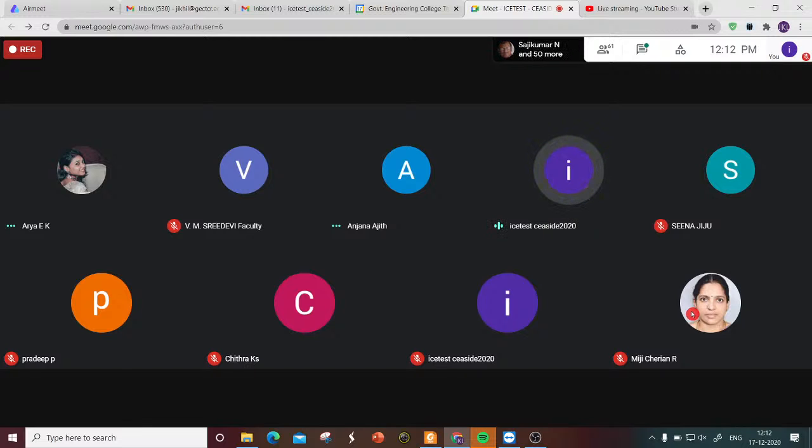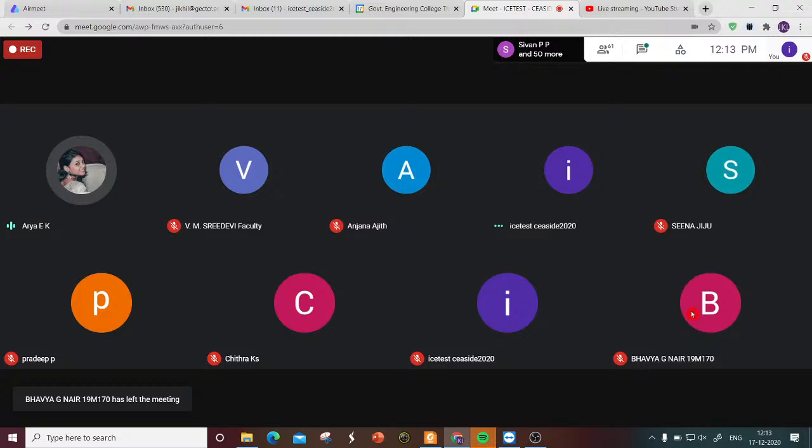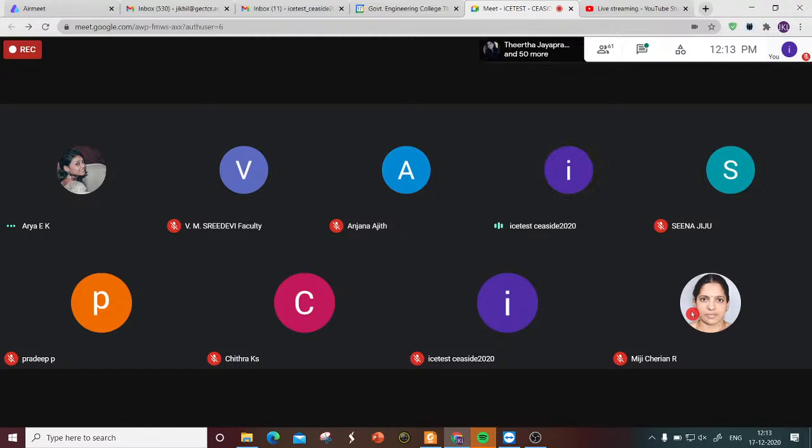So this one, corrosion control, what are the different corrosion protective methods nowadays, the most popular one? Yeah, that's what I have explained. The most popular protection method was patch repairing, but we cannot stop by just repairing one side of the degraded concrete. So we have to continue if patch repairing is adopted, which is not at all feasible. And now the clients as well as the contractors have realized it and they have moved towards the sacrificial or cathodic protection side. So mostly it is now getting popular. And we are trying to look at that in India, I mean on the research side.